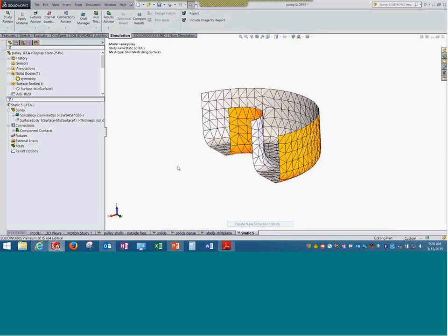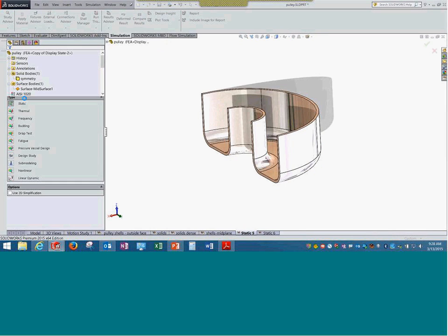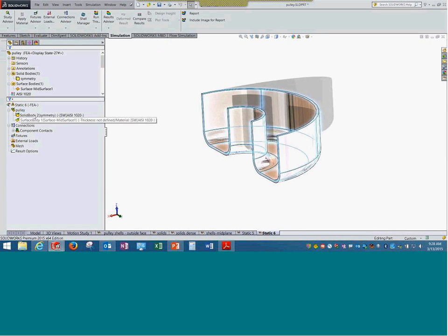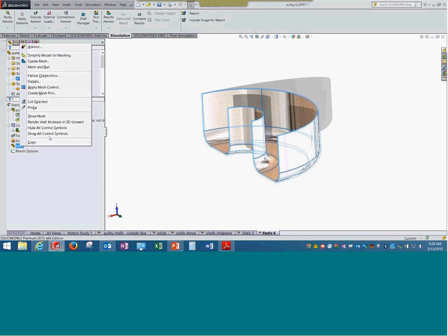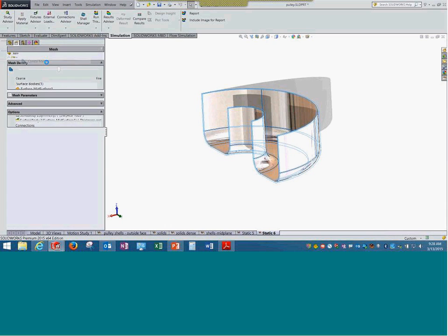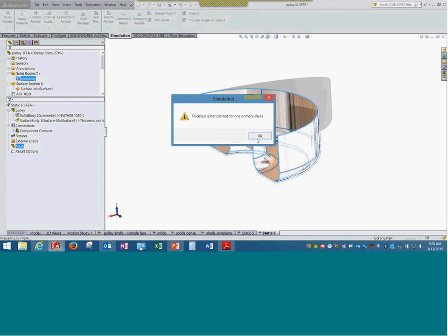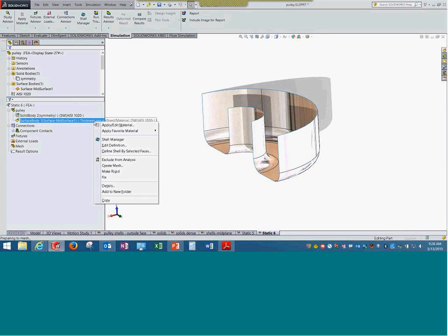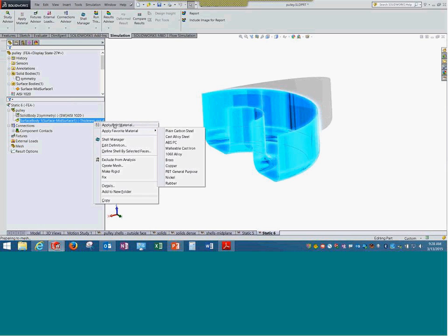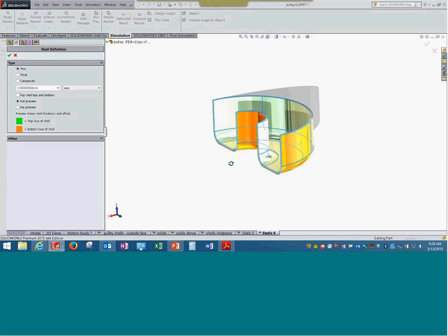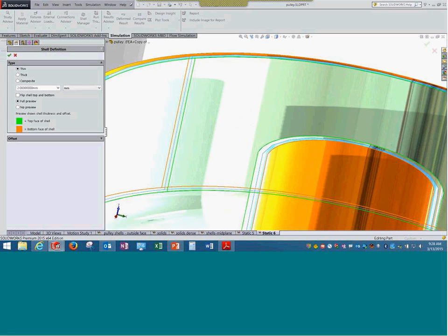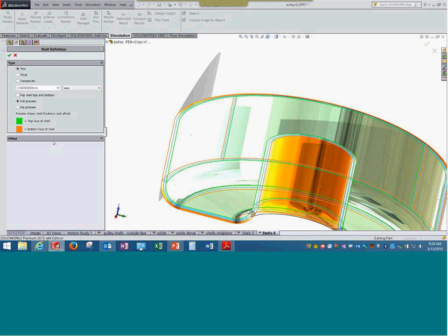The second one could be a bit different, wherein you already have a surface, no big deal. Let me get rid of this part and I directly mesh this surface geometry. Okay, error. Yeah, I got it. So the thing that you need to give over here is the thickness of this particular surface geometry. No location, assuming that I took care of it when you did the CAD geometry, right? So this is it, and accept it.